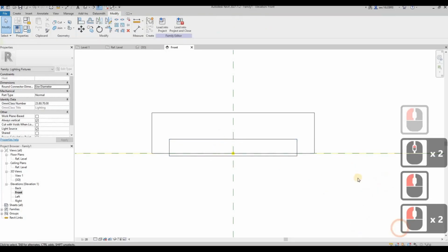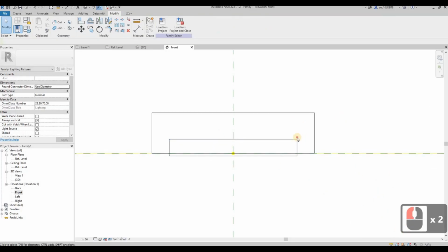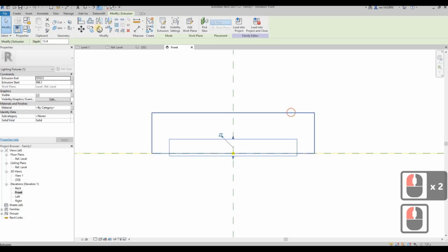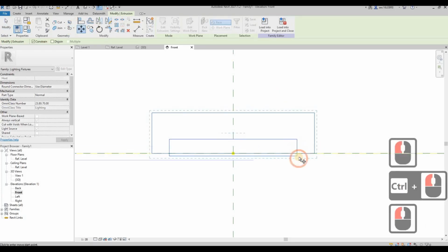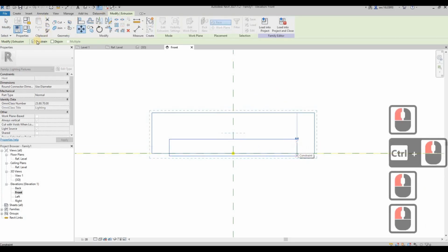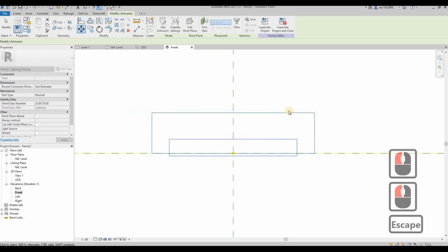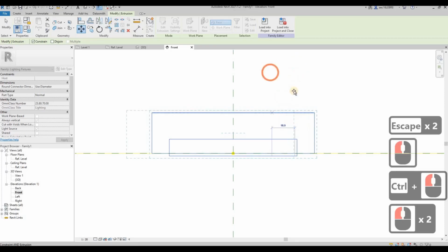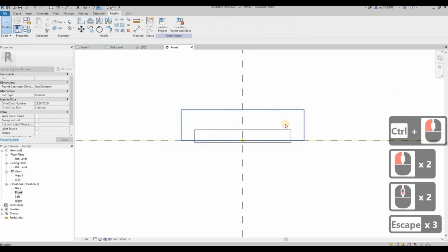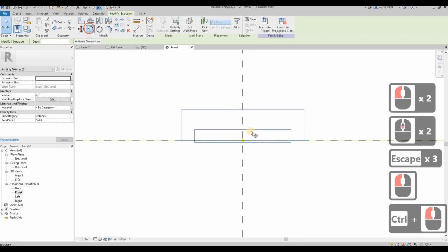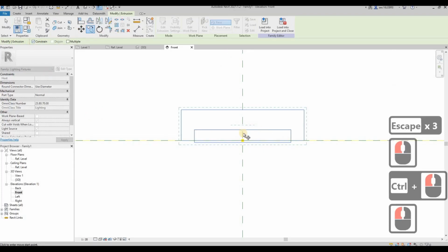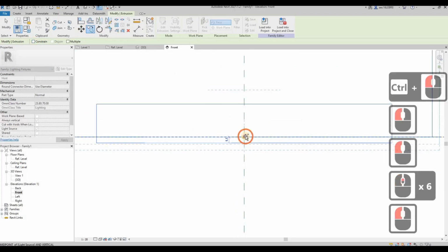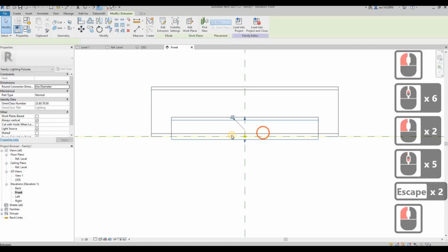But if you have covered up the light source, okay, then you need to further increase the height of these two items. Okay, sometimes you can't move your extrusion up. Okay, so what you need to do is just use a copy function, remove the constraint, then you copy this up here, then you delete the original one.